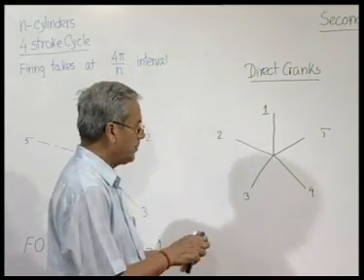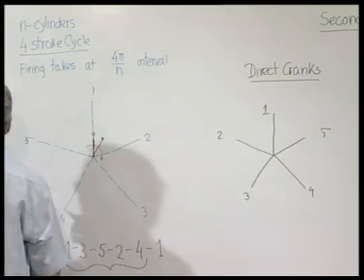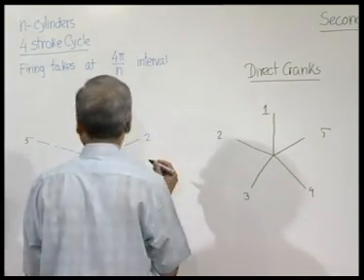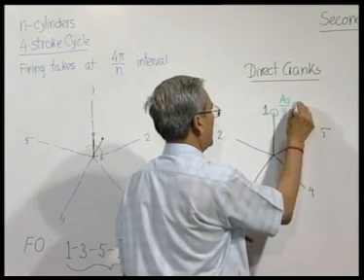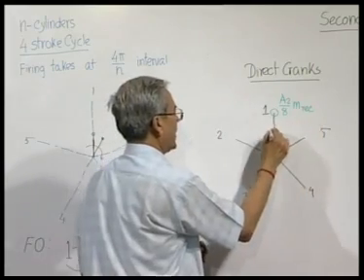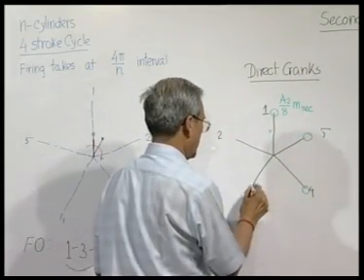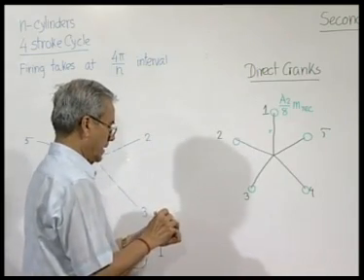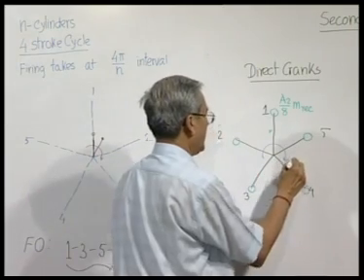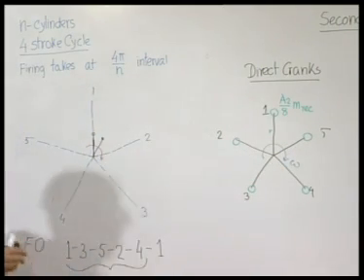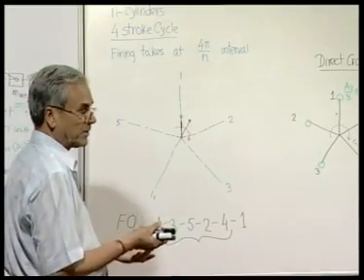Now you see that if we place, how much mass do we have to place? A2 by 8, and this is R. Same here, same here, same here, and this is the direct crank. They are all rotating in this direction at speed omega. The centrifugal forces produced by the eccentric masses placed at the crank pins of the direct secondary cranks are balancing amongst themselves.